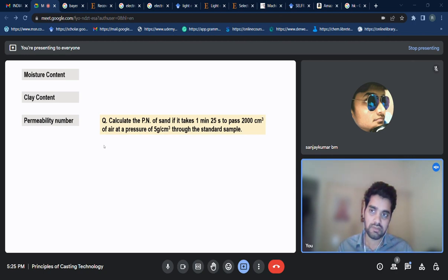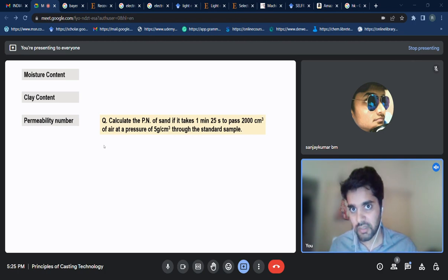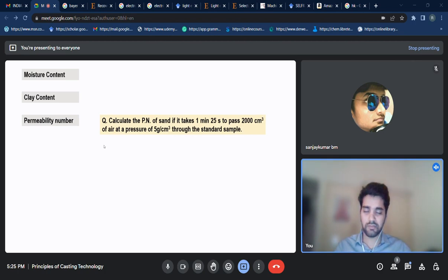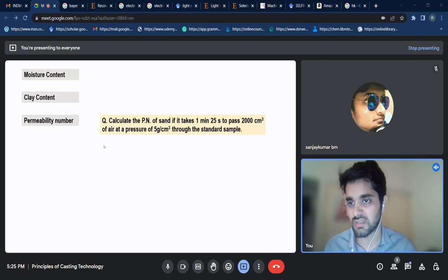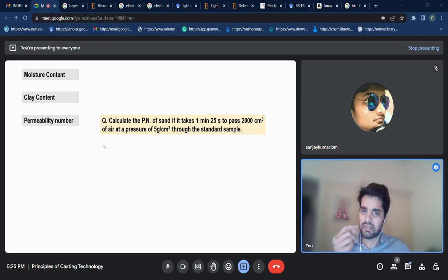As the clay content increases, this is how a liner is made: they mix sand or some other material with some percentage of clay, like 10%, 15%, 20%. Firstly, in lab scale, the clay content is optimized for strength, permeability, and crack propagation. These three things should be optimized, and firstly it shouldn't crack. What's the problem with clay? I will give you the example of multani mitti, which some of you might have seen people putting on their face.